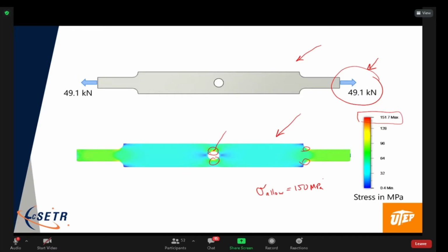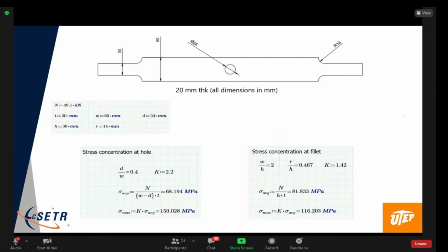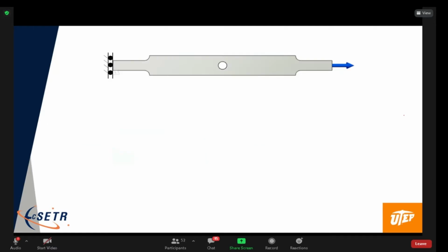All right. So it works out quite well. The stress concentration factor really does do a good job. Like this is, you know, 1% error, 2% error, which is pretty good for a finite element simulation or a hand calculation, right? So, okay, so here I just did all this stuff. So, okay, so how did I want to set this up in Fusion?